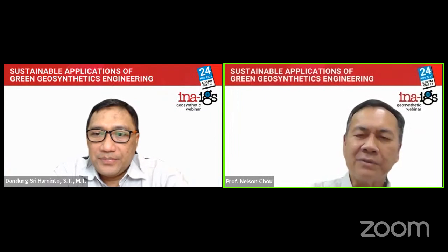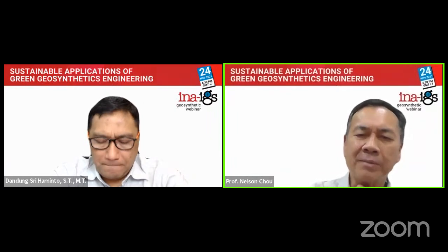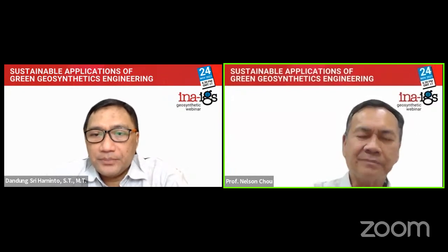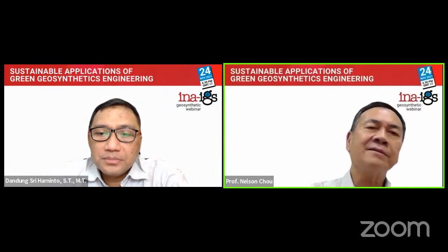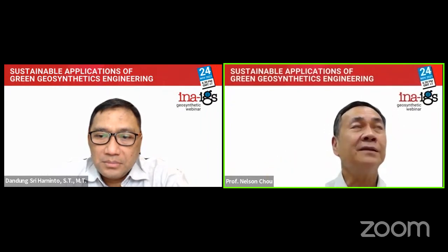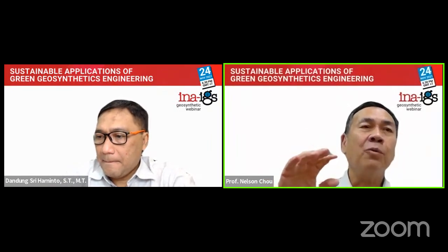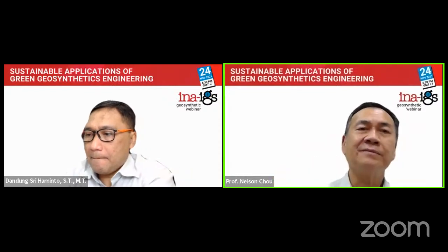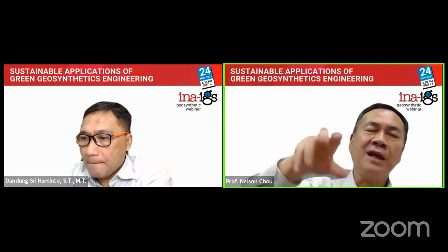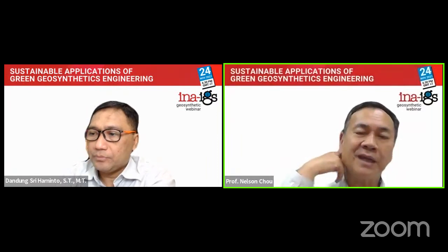I don't understand what geosynthetic materials in a railroad embankment in controlling surface erosion means. For surface erosion, you can use geosynthetic, but you don't really have to. You're talking about the embankment surface, not the top. Okay, embankment surface. Using geonet. I think I showed one case. We put one layer of geogrid, then put another layer of wire mesh on top of the geogrid, then put the geonet to anchor to avoid sliding. I think my picture used that.